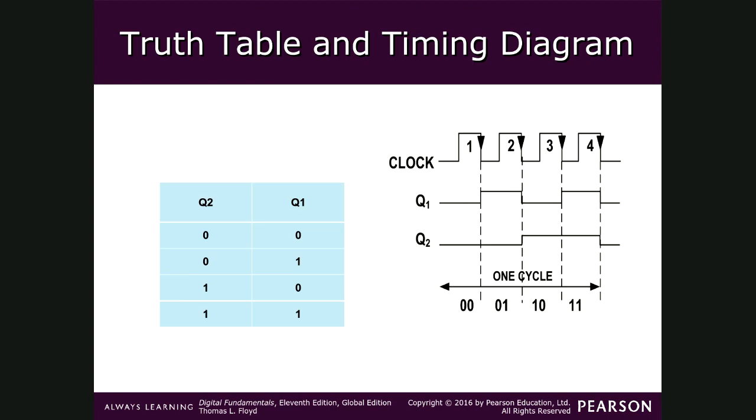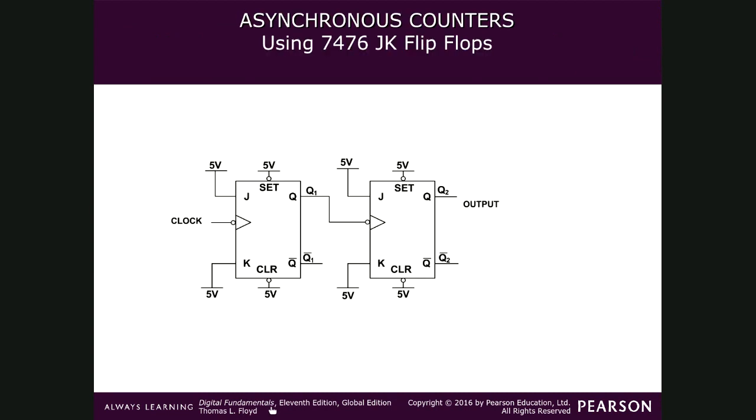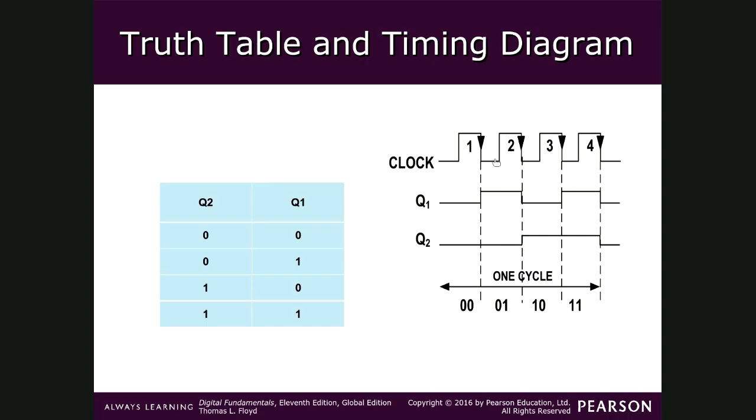Take the pointer. So this is the clock. So 4 clock pulses. The first flip-flop, because see here, J1 K1. In a JK flip-flop with J1 K1, the output will be toggled. Initially it is 0. The first clock coming, the output will be toggled, and the second clock again toggles, and the third clock toggles, and the fourth clock toggles.